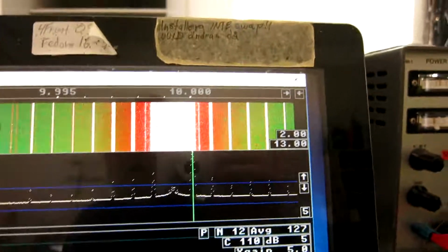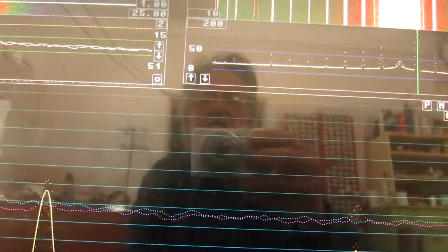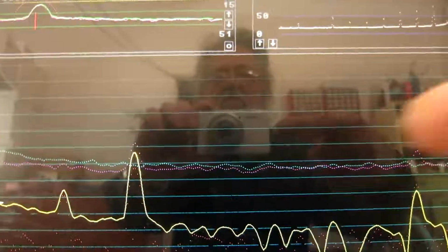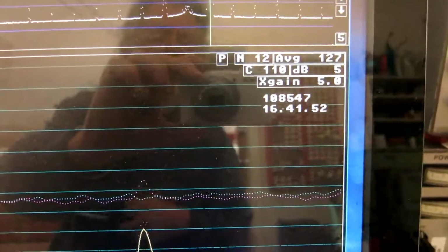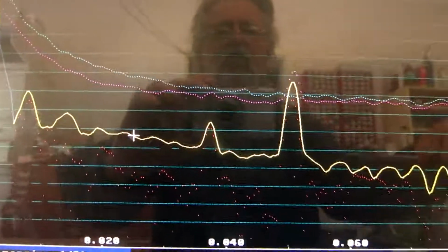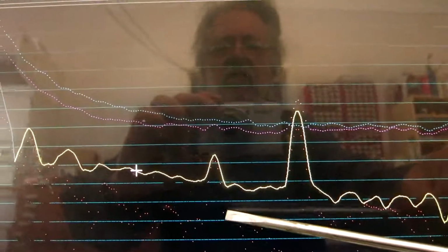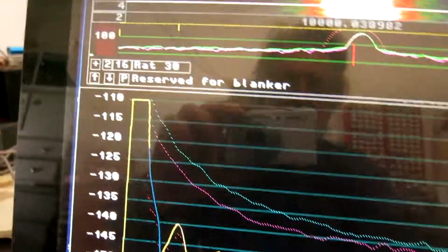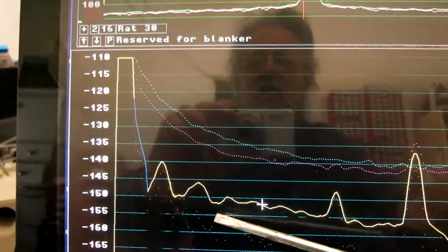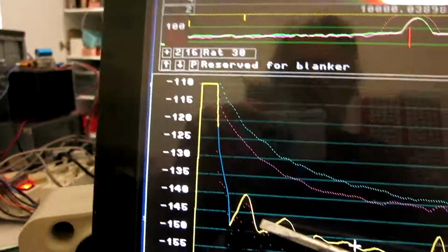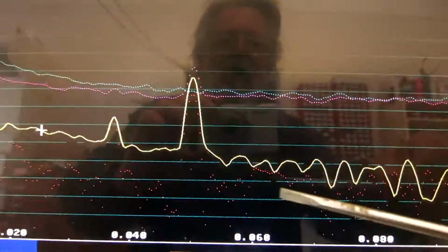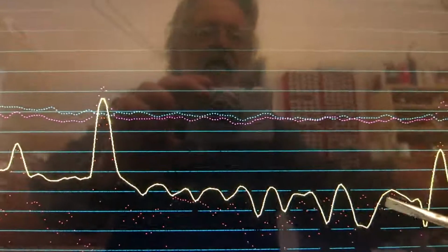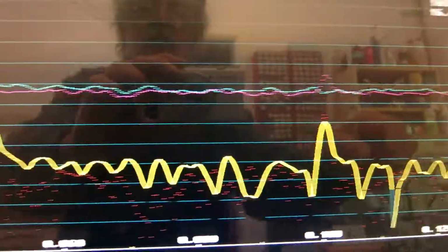So signal to noise ratio of the direct signals, the average power spectra here, has degraded significantly. This measurement has been running for 16 hours. I estimate the noise from the imaginary part, and it's down here, but at about 20 Hertz it starts to come too close, and at 10 Hertz it's about the same as the signal. And at wider separations the signal is the same as the imaginary part.